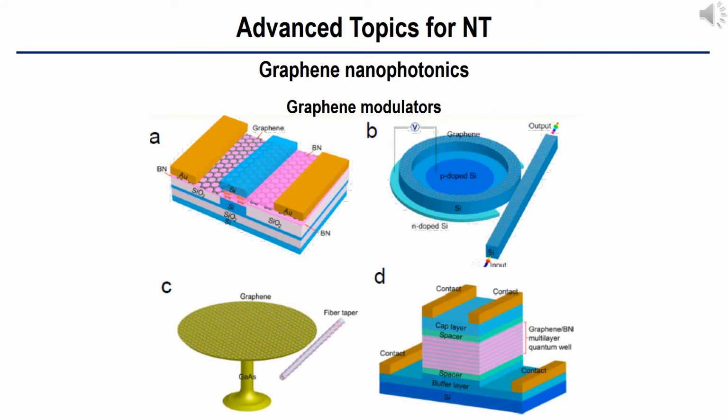Graphene-based modulators have different forms. For example, for a waveguide-integrated graphene-based electroabsorption modulator, the modulation can be done by actively tuning the Fermi level of monolayer graphene. For this structure, a 250 nanometer wide silicon waveguide is connected with 50 nanometer silicon to ITO electrode. A 7 nanometer dielectric spacer is followed by a mechanically transferred graphene sheet. A counter electrode is connected with Pt, as shown in the upper left figure.